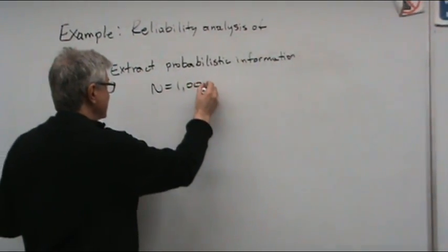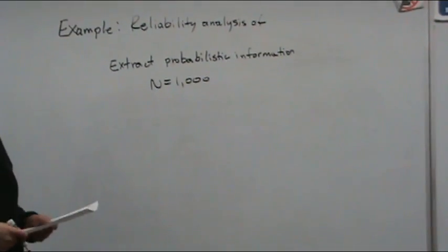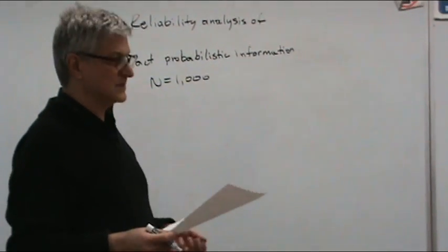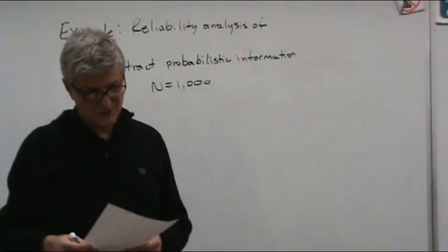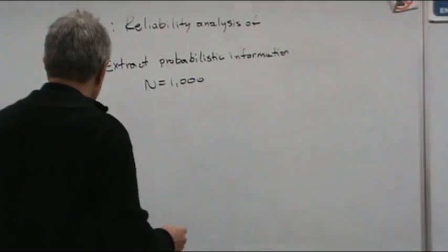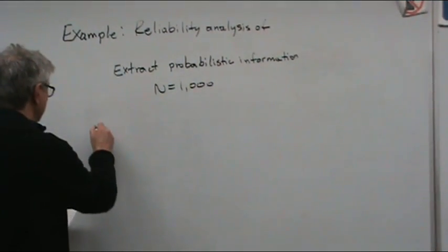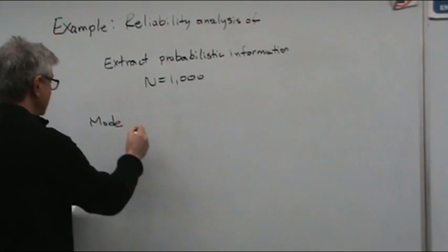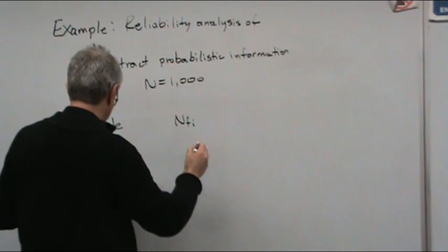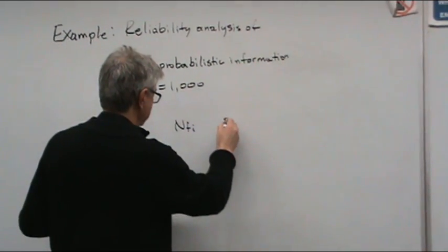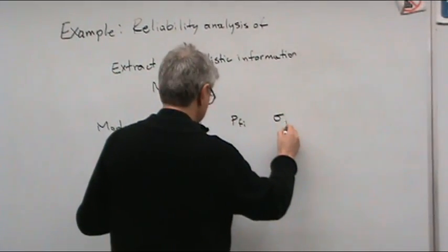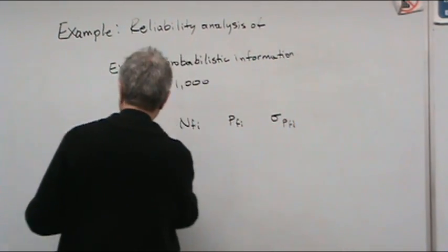I did 1,000 replications, standard Monte Carlo simulations. The simulation generated random numbers for the loads. And here are the results. We have failure modes, the number of failures observed in 1,000 replications, the probability of failure, and the standard deviation of this probability of failure.